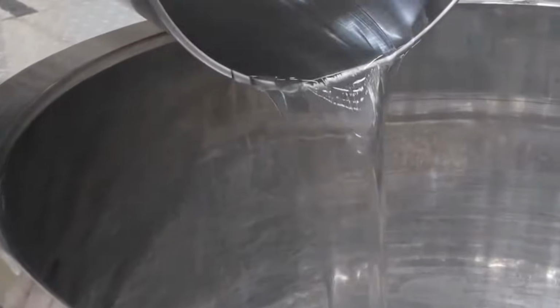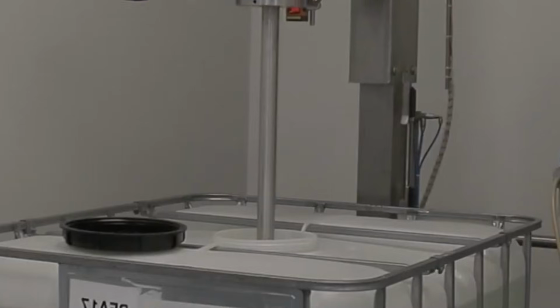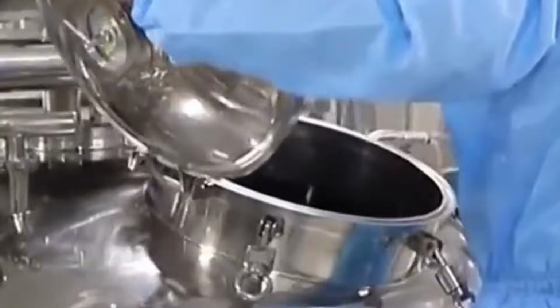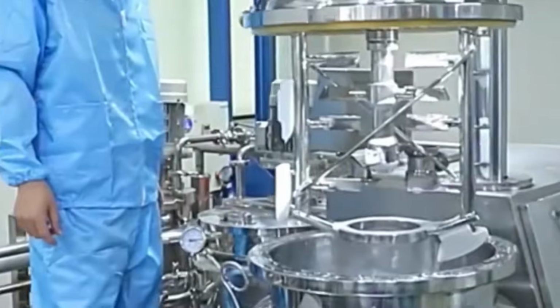Bottles proceed to the labeling station. Labels may be pressure sensitive, shrink sleeve, or wraparound types. Pressure sensitive labels are applied using rollers and air jets, with registration controlled by optical sensors. Shrink sleeves are applied loosely and then passed through a heat tunnel where they conform tightly to the bottle shape.